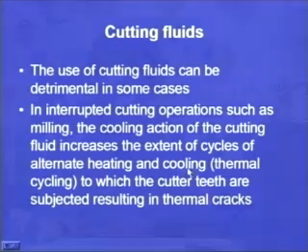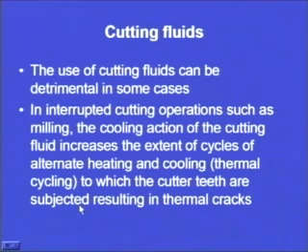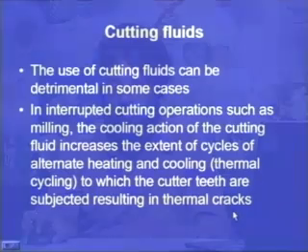So, one particular cutting tool is going through alternate cycles of heating and cooling. That we call thermal cycling, to which the cutter teeth are subjected, resulting in thermal cracks. This thermal cycling may result in thermal cracks and may finally lead to tool failure. So, under such circumstances, we can avoid the use of cutting fluid also.